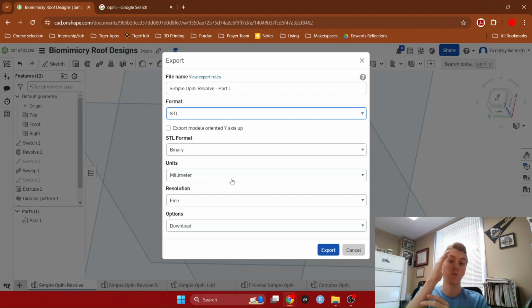It's saying that 1 inch is like 25.4 millimeters or however it is. And then it makes it so that the 3D slicer software can understand the size because most of these softwares use millimeters. And then that's how we're going to 3D print it. So we take our STL file, put it into the 3D slicer software, and then we're done.